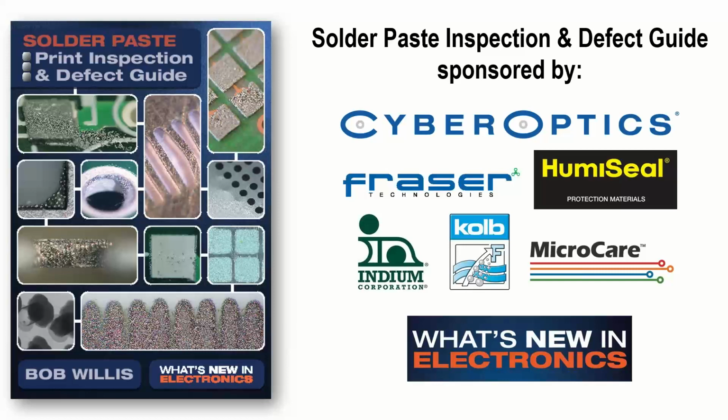Some of the manual ones, you have to do it yourself, but they must be in the same place, exactly in the same place, time after time after time. So you need alignment plates or something to guide you to that position. Next thing is that as you go down in thickness of boards, then there is distortion purely by the pressure applied to the surface by the stencil and then the blade and the printing process. Then you need to perhaps think about other methods of support.